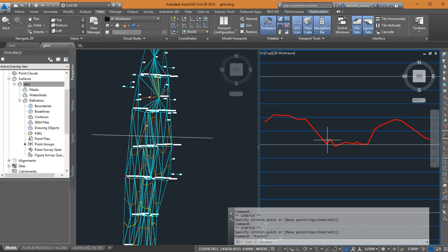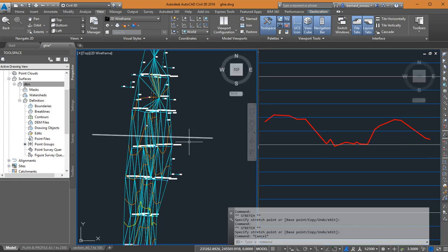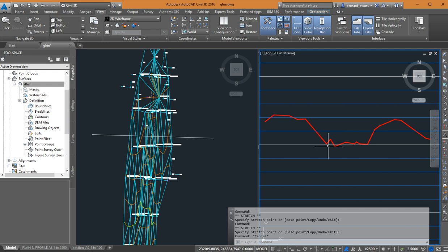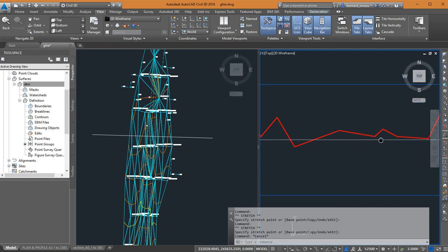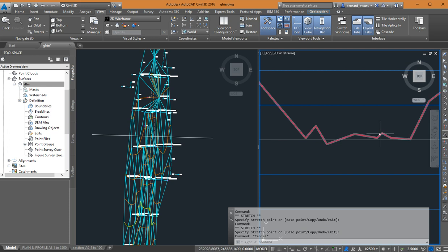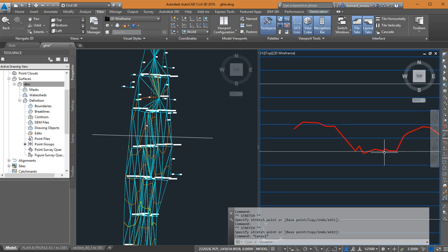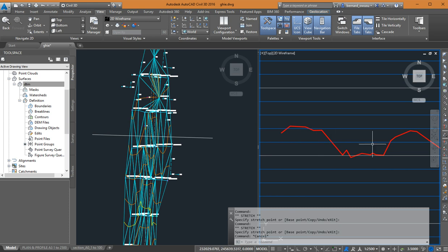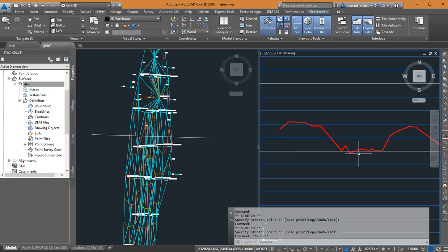Please, are we okay? We are going to use the road edges and the center line as break lines so that we'll be able to refine. Because if you look at what is happening here, it could be that there's something wrong somewhere here. Because you cannot have a road like this. It's likely maybe this one ought to go straight or something. But we can see that this place is in an embankment. I mean, in a cut.